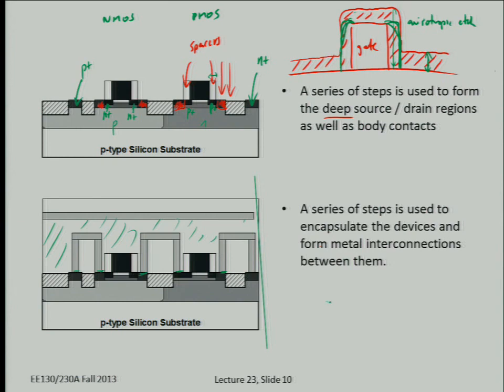Okay, so remember a practical ohmic contact. These wells are not very heavily doped normally. The channel region of a MOSFET is not doped like 10 to the 20 or something like this. Usually when you're trying to make a contact between silicon and metal, there's always going to be some Schottky barrier height. Let's say for a contact to N-type material, you have a Schottky barrier height for electrons. To get current to flow into or out of the silicon, you have to make that tunneling barrier really narrow. So you have to locally dope the silicon very heavily. In order for the metal to have an ohmic contact to the wells, you have to dope it very heavily at the contact, only at the contact.